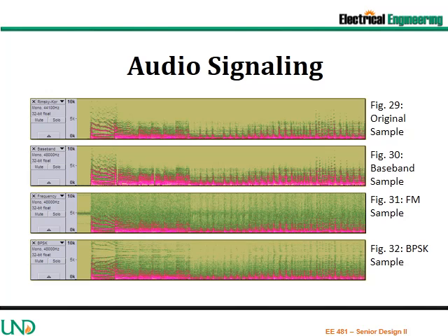The frequency modulation is performed in software with amplitude proportional to period plus an offset. 167 kHz is the lower frequency, and 500 kHz is the higher frequency. These were chosen to reduce processing complexity as the periods for these frequencies were multiples of the clock speed.